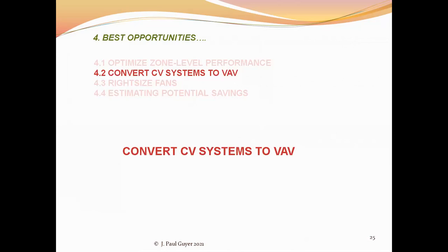And there are basically three factors that affect the feasibility of implementing a VAV retrofit. These are the cost, the annual energy cost savings, and the building owner's requirements for a rate of return on his investment.